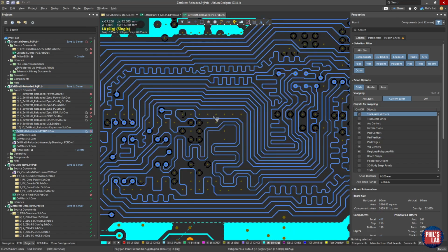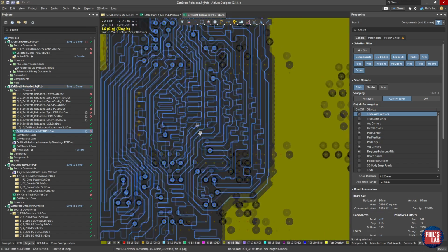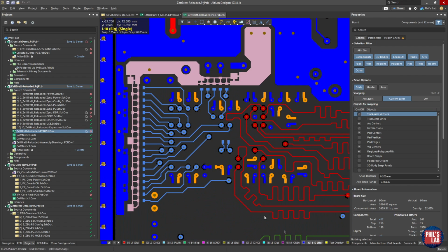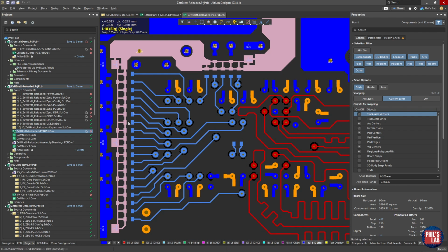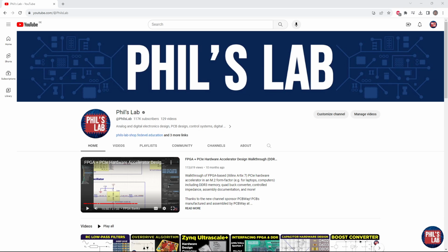In terms of layout and routing, go to 2D view, then we start at the host controller, these blue traces. We route over to our first memory module, we route over to our second memory module, and then finally, as short traces as we can, again trying to keep them as lumped elements, from the last memory IC over to our termination resistors scattered close to the device and placed sensibly. In this way, despite fast rise and fall times and the rather lengthy traces, we can minimize the reflections in this system.